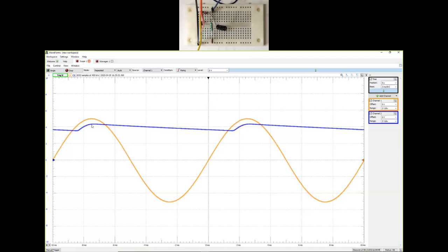So this goes down until the next charging cycle comes in, which is going to be only the positive half cycle, because we have already eliminated the negative half cycles. So that's your smoothing with the 4.7 microfarad capacitor, and this is for a frequency of 100 hertz.